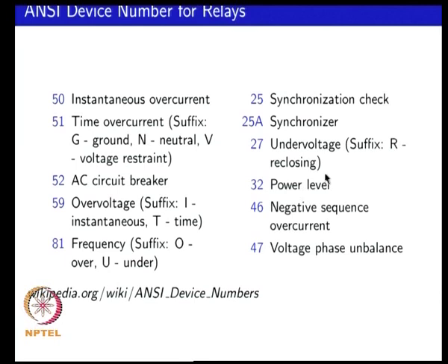Okay. So, you would have relays for functions such as that. We also saw that you could have relays which operate as a function of power level. So, you calculate the power level. If it goes too high, you might be at an overpower condition. Also, if the power goes negative, for example, we saw an example of an anti-islanding function where we look at the sign of the power. If it is going negative, then you could potentially detect an unintentional island. So, that would be a reverse power relay.